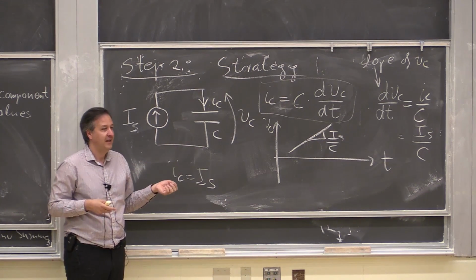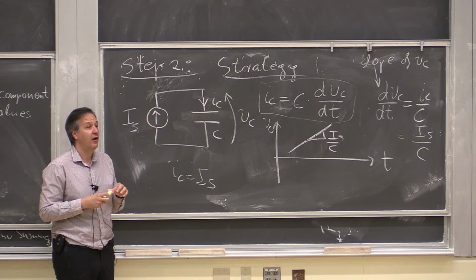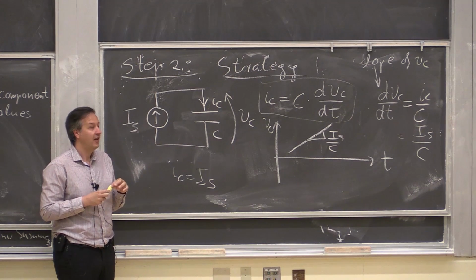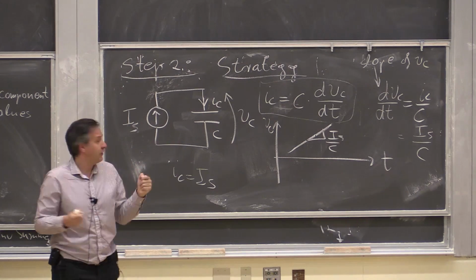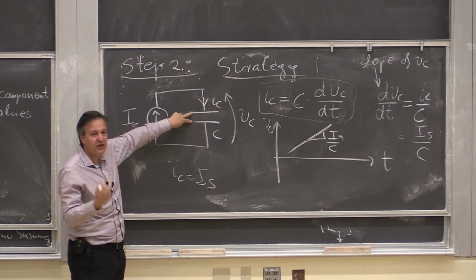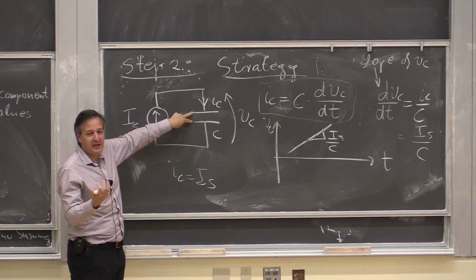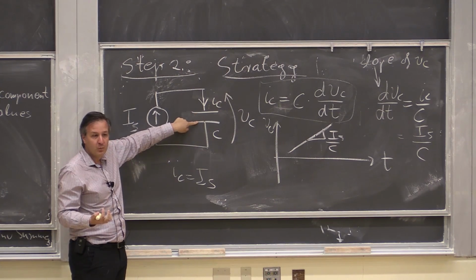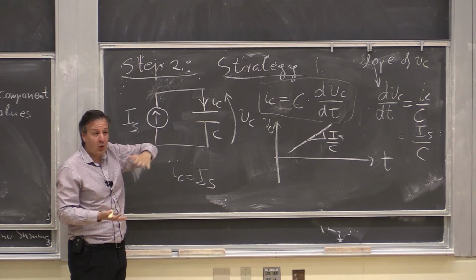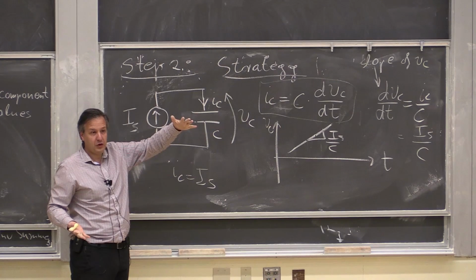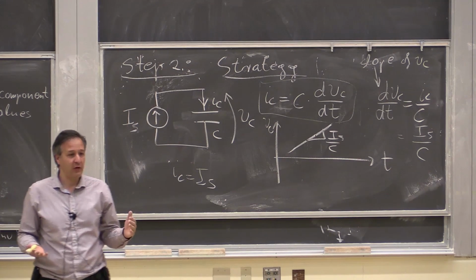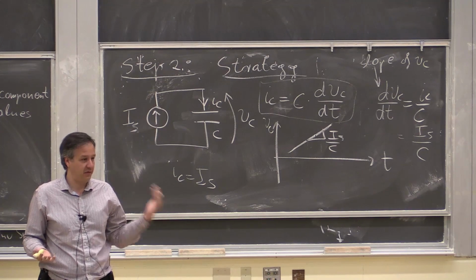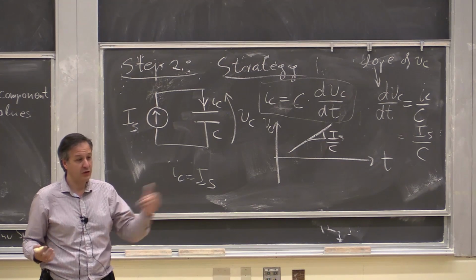Discharge. Discharges through the air. Through where? Across the plates when I'm leaking. Yeah, so as the voltage increases and this distance is fixed to L, there's an electric field in here that grows with increased voltage. And essentially, at some point, you will hit the so-called critical field where air is going to discharge.